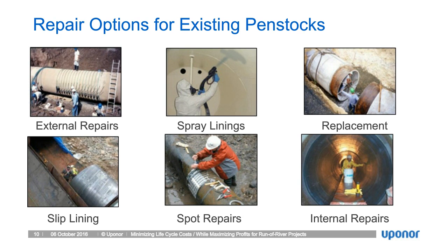Spot repairs, just quickly, would be a coupling clamped onto a pipe. Again, it's a band-aid to possibly a much bigger issue. Internal repairs, typically using carbon or glass fiber or FRP, in which to do spot repair, surgical repair inside large penstocks. The pro is that it's a good interim solution, but it is very costly.